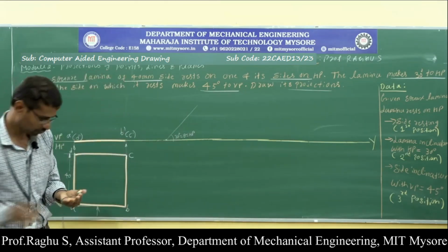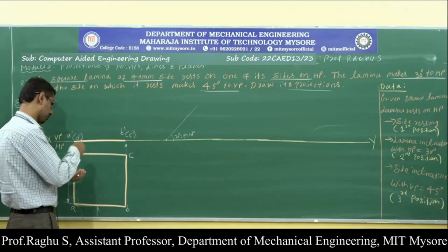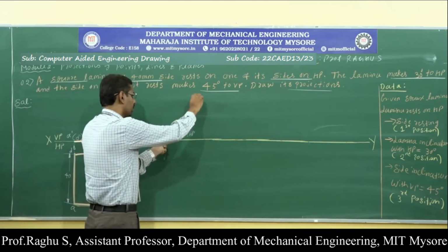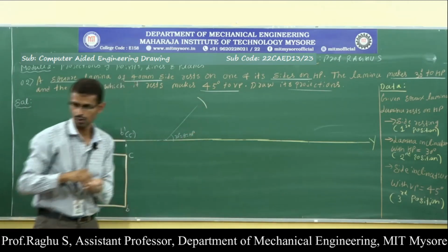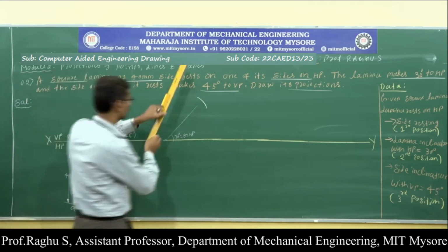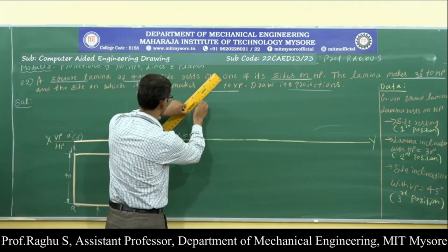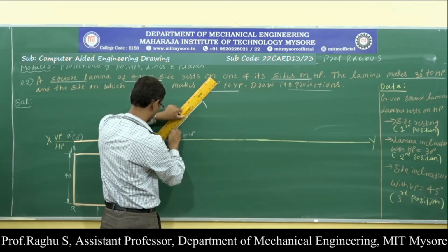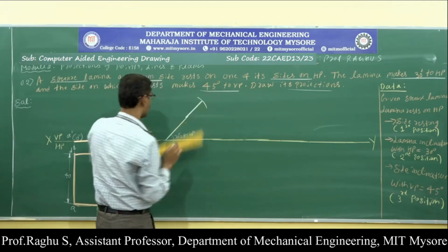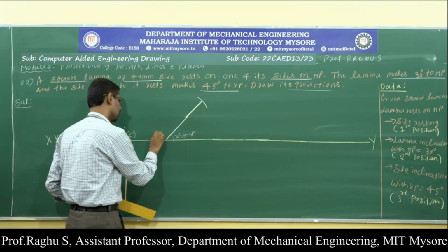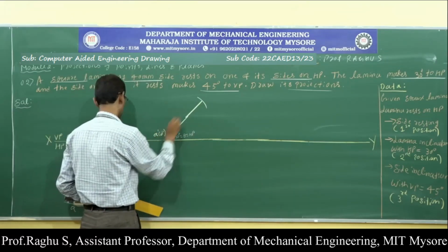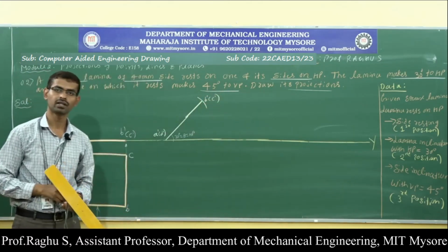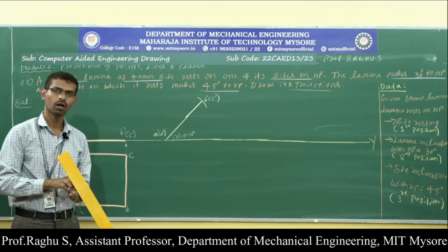Right. Now, measure this dimension. So measure this length from this point. Cut an arc. Now, make it dark. Here this is A dash and D dash and this is B dash and C dash. Now I have completed this second position front view.